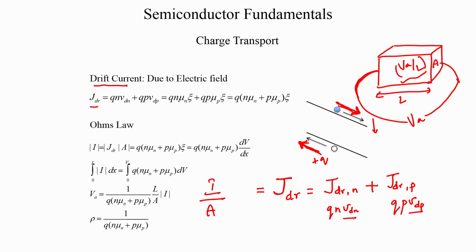We have already looked at the concept of mobility of carriers. With the electric field and the drift velocity of the carriers, at low electric fields the drift velocity is linearly proportional to the electric field, and then it saturates in some of the semiconductors. At low electric fields, Vd is proportional to the electric field, with the constant of proportionality being the mobility of the semiconductor.